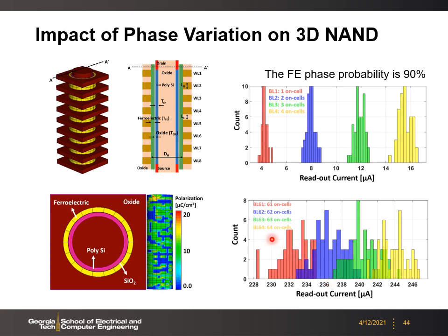For example, here, 64 cells. Ideally, for the full precision, we may need 6-bit ADC, but if we only use 4-bit ADC, then we don't need to differentiate such overlapped distribution. We only need to distinguish between the cells on states 64 versus 60. Therefore, the overlap effects will be ignored.